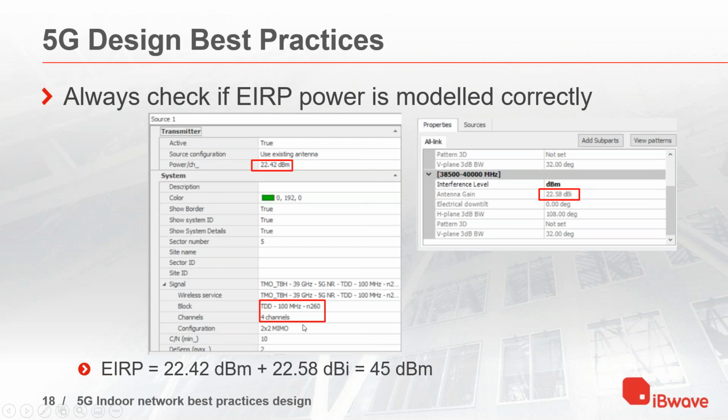Remember when I was telling you about plus and minus 45 degree polarization, that's that. Basically what this is telling you is that you're going to have 8 RF beams, and those 8 RF beams will be spread out over 4 different channels, and each channel will have 100 megahertz. So you are covering a total of 400 megahertz here.